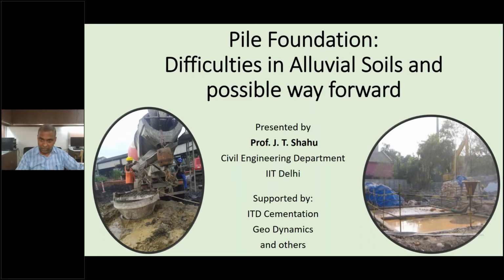They started with driven piles. First of all, for driven piles, they had to bring the equipment and transport it to the Indo-Gangetic plain, Delhi, from Madras. They told me that it took 1 month for that truck-mounted equipment to move to Delhi. Then it started, and it got stuck after the pile had been driven halfway. So then we went for ground improvement methods and then constructed the structure. But suffice it to say that that was the beginning, around 2005 or 2006, when pile foundations on such a large scale started coming up in the Delhi region. And now we have multi-story buildings, 40-story, 60-story buildings, which are left and right working on pile foundation.